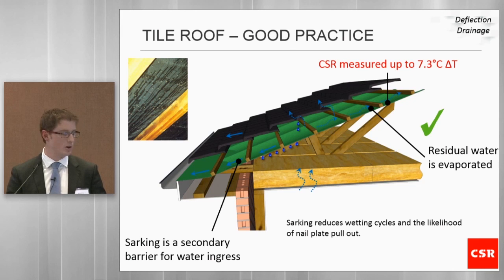A large culprit for migration of humidity from the living space to the roof space is ventilated downlights. They'll allow all the heat and all the moisture from inside the house to go straight up into your roof space, increasing the potential for condensation in any roof system.